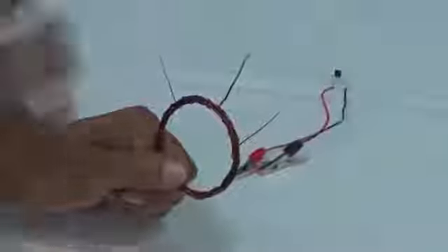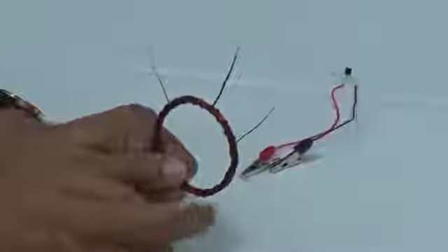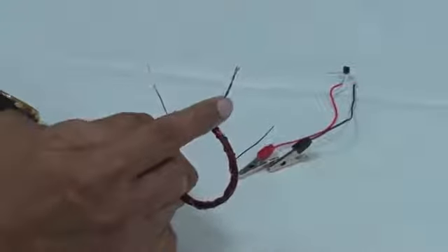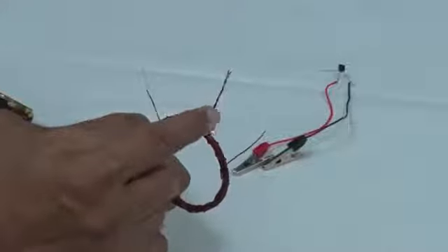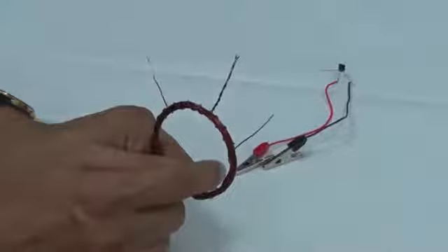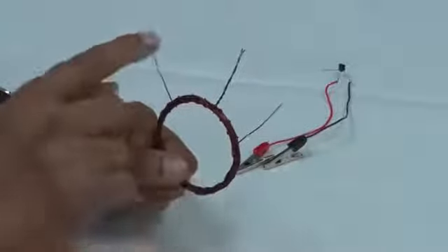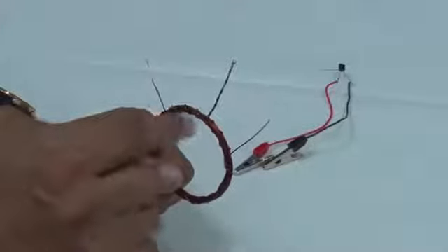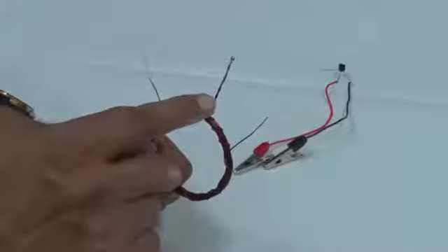What we have done is this 30 turns total. So starting from here, we make 15 turns, and after 15 turns are over, the same wire is taken here, and then this part is taken out, tap, central tap, and it continues. Again we go for another 15 turns. Okay. So, the ends of the coil are here and here. This is a 30 turn coil, ends are here and here, and from middle when it was 15 turns, that time we have just taken that wire out and then continued. So, that is how the third terminal is made.